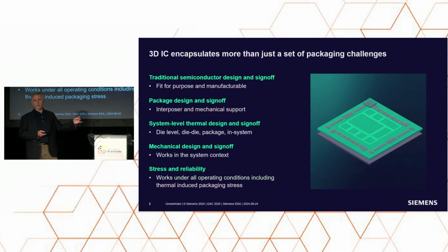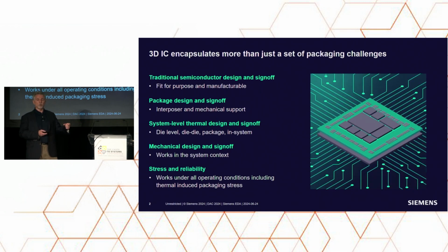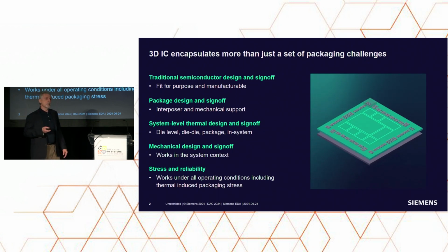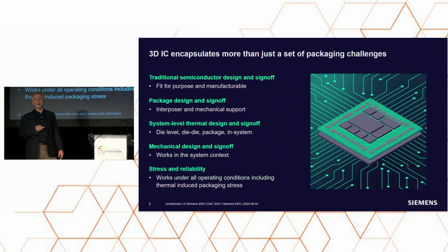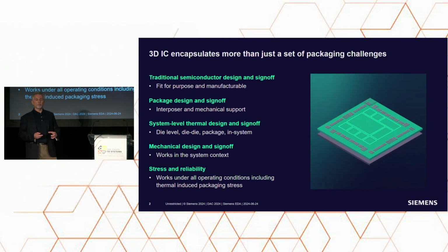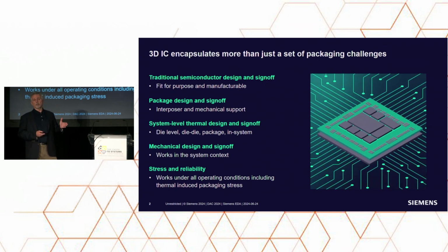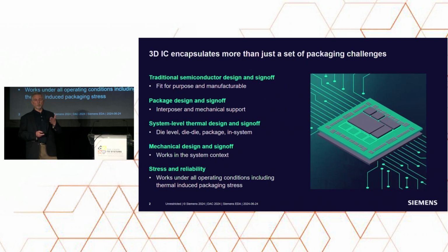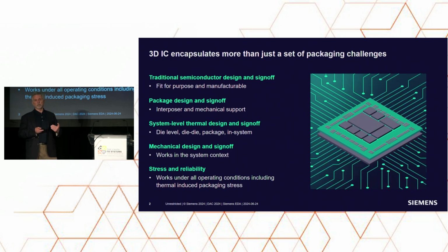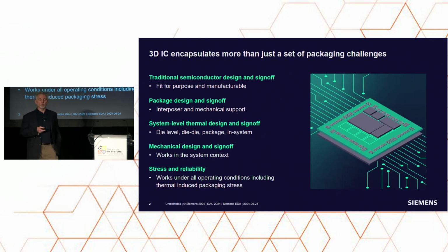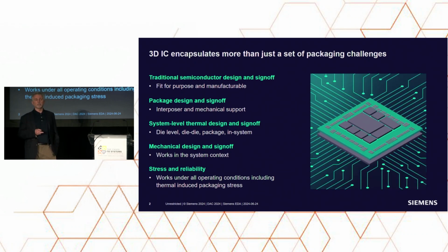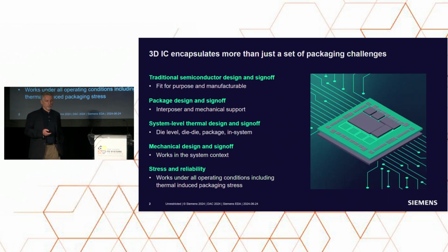So you can have one chip that's specialized for digital, another one for mixed signal, and you can even mix non-silicon technologies such as gallium arsenide. Another term is "More than Moore." With Moore's law, we're hitting diminishing returns on how big we can make a chip. There are physical limitations, but also scaling. Making transistors smaller and smaller means you could put more in a system, but we're hitting limits where the cost is increasing, and the power is increasing. So this packaging technology enables us to extend some of the limits of Moore's law.